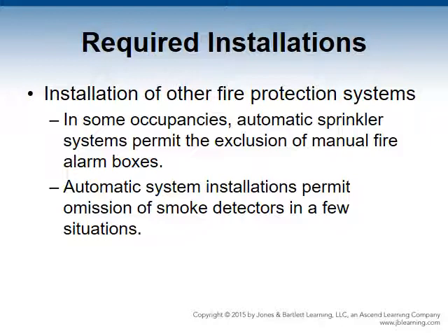Installation of other fire protection systems. In some occupancies, automatic sprinkler systems permit the exclusion of manual fire alarm boxes, as long as the notification appliance sounds an alarm when a water flow alarm activates. Automatic system installation permits omissions of smoke detectors in only a few situations.